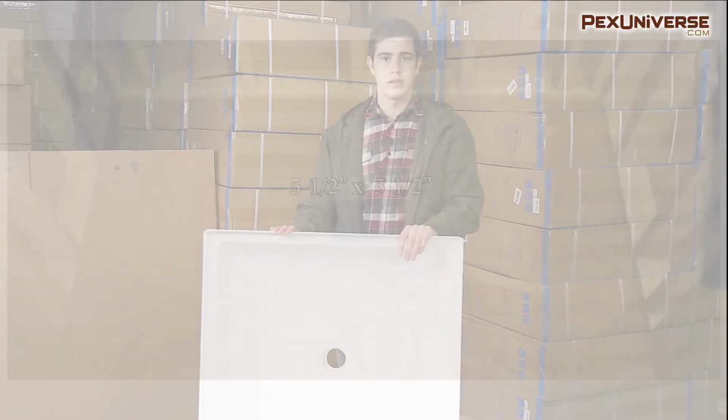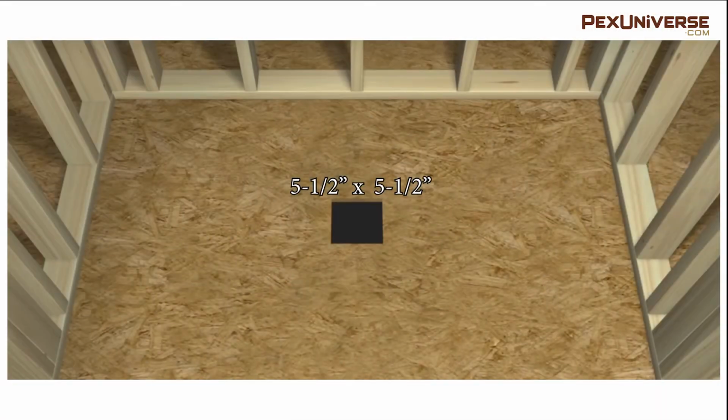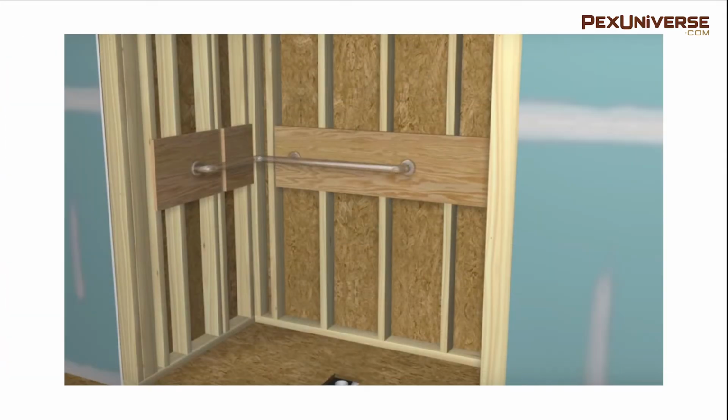After you've constructed the alcove and finished rough plumbing, cut the drainage pipe to be level with the subfloor and secure it in place. Note, this shower base has an integral drain, but others may need the pipe to come up higher than the subfloor. Check your installation guide if you're unsure what will work. Additional support for optional features like grab bars and/or seats should be installed now before the walls are put up. Refer to the installation guide again for proper or ideal placing to allow the best experience.